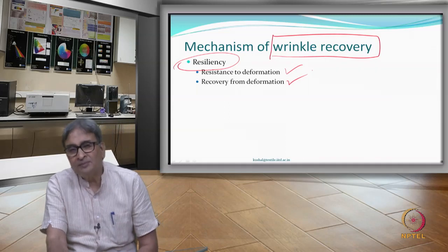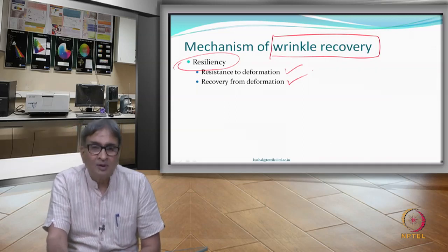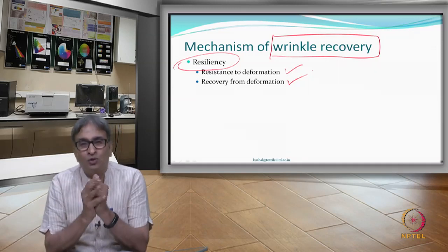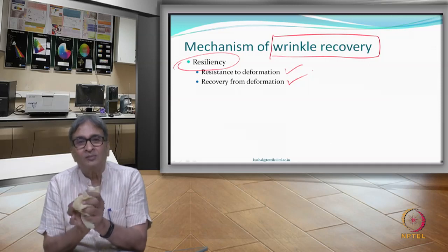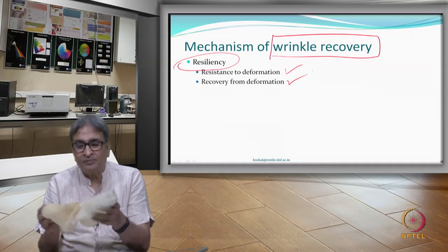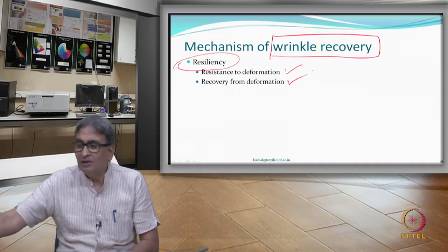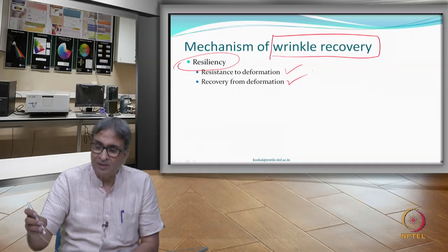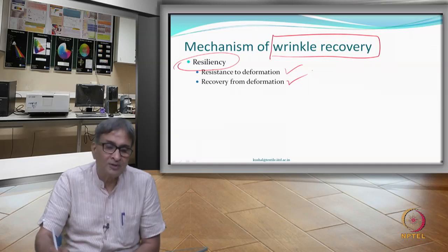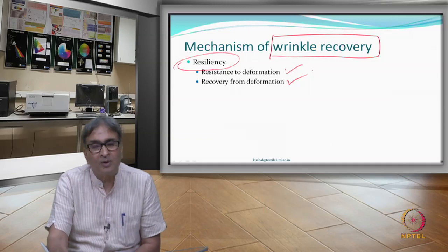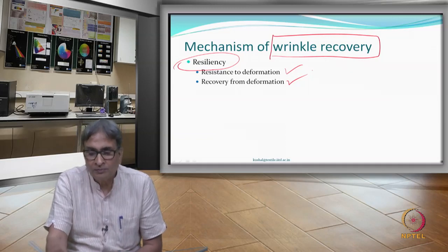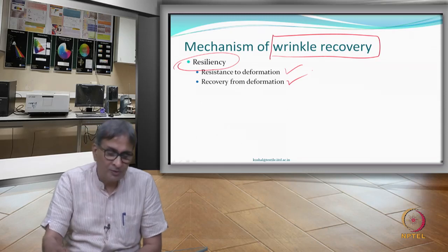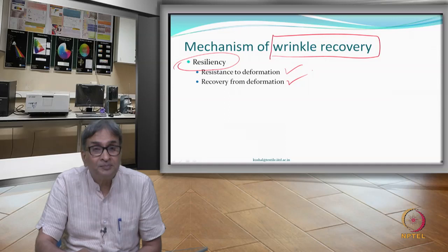Now, a textile fabric can resist, of course, but the forces like this are too harsh and too strong for it to resist, but it can recover. If it recovers, then we will find that the crease visibility becomes less, because it recovers from the crease. Crease can be formed because mechanical forces could be strong, but recovery is the one which we are going to be more concerned about.